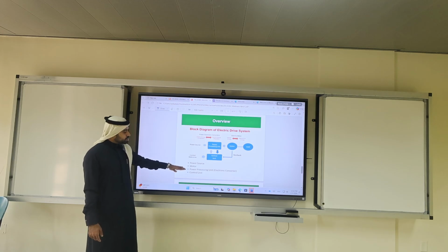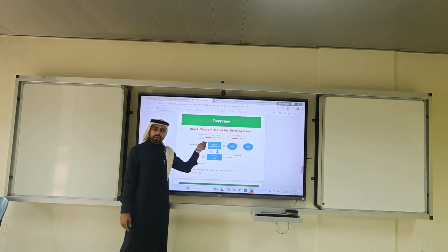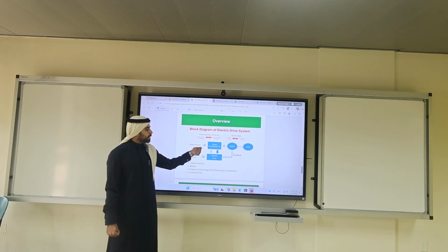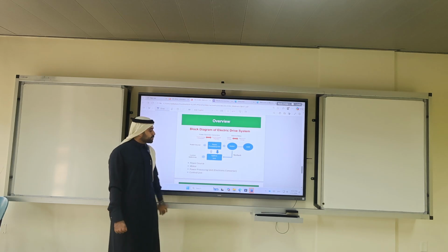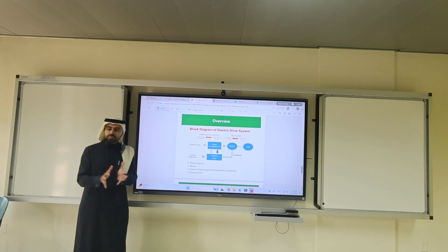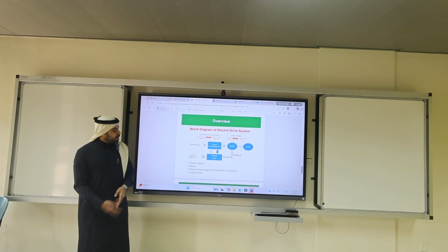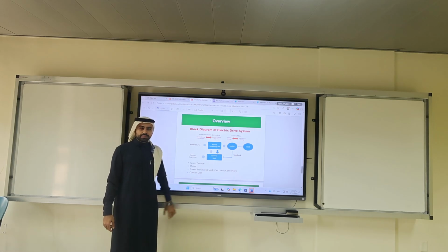So we usually have a power source, motor, power processing unit, or electronic converter. This is where we put a diode, a rectifier, we put a transistor. IGBT, for example, is commonly used. We put in MOSFET. If you studied 203, remember MOSFET. But those are power electronics, not small 0.7 volt diodes, but larger diodes. And the control unit is a microcontroller, usually like an Arduino, for example. Okay?